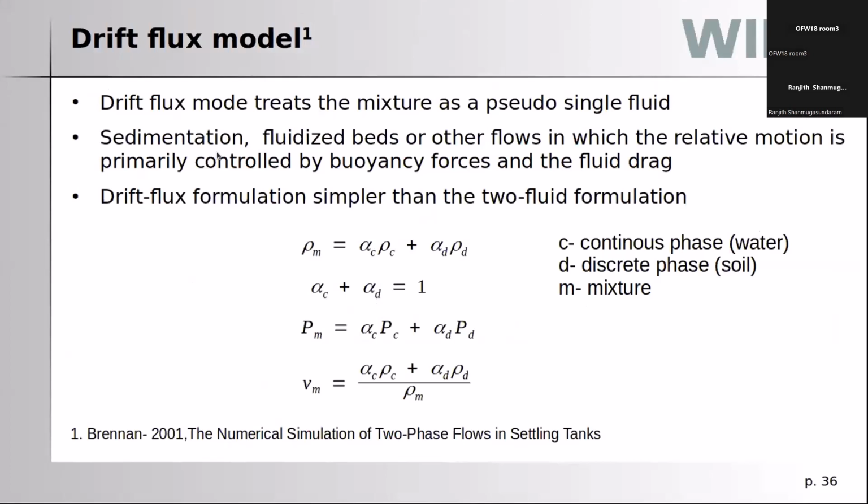In that, it treats the mixture as a single fluid. Instead of having two different phases, it is considered as a pseudo single fluid. If you have to do it for two phases, you will have two momentum equations, two continuity equations, and a momentum transfer between them. But this driftFlux model solves as one single fluid, so you have one continuity equation and one momentum equation.